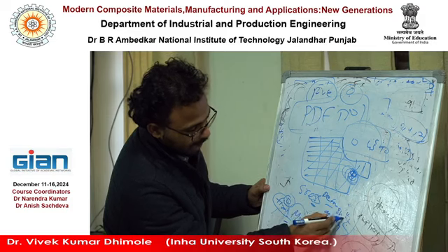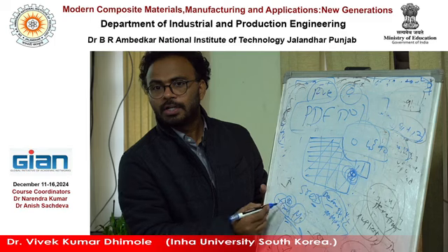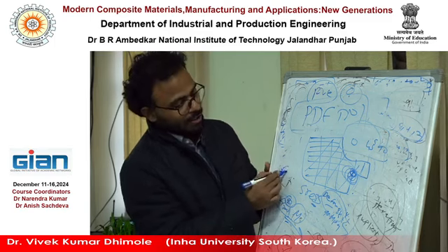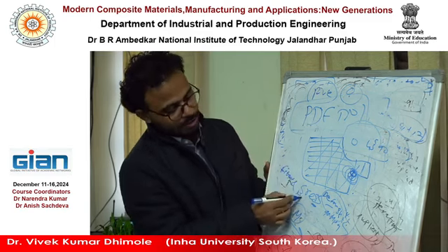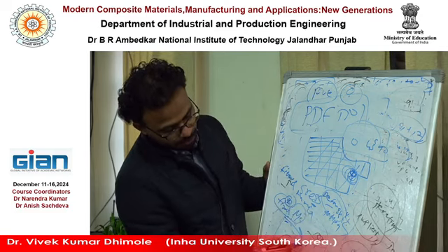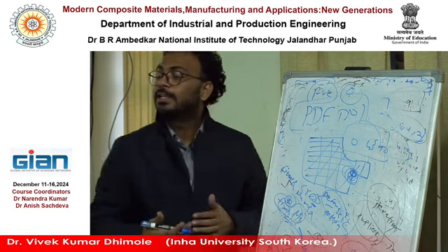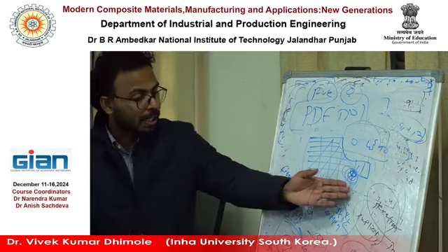Deformation is strain. Apply this deformation, calculate the deformation at this small part. Then you get the result at the fiber and matrix. How does it behave? Maybe this stress is now 90. Maybe this is 120, inside is more, right? So like that you can understand the inside, macro to micro.